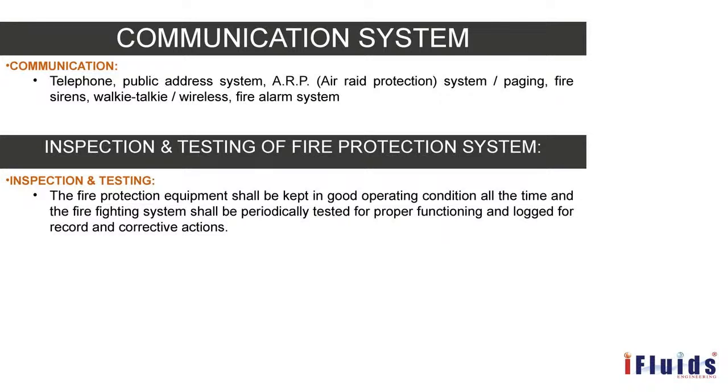Then, once a month, each pump should be checked for shut-off pressure and auto shut-off condition. All these things are mentioned under this fire water pump criteria with respect to testing. If it is a fire water ring main, then all the fire main valves should be checked for operation